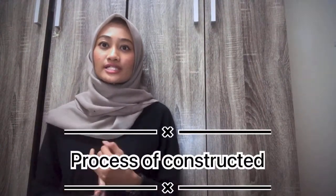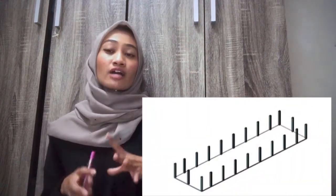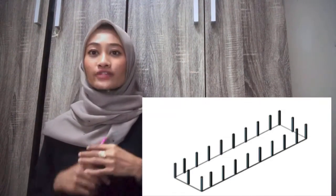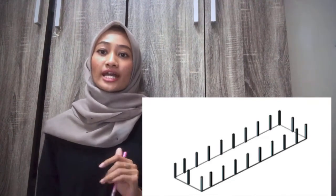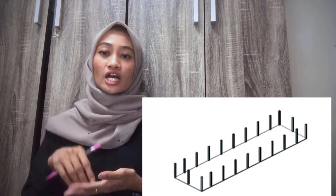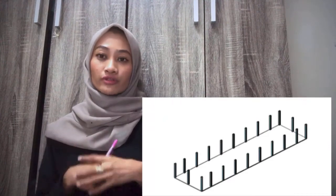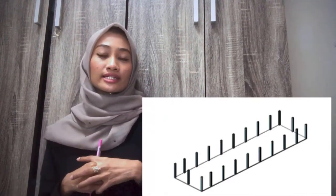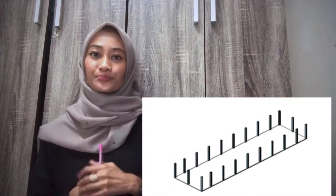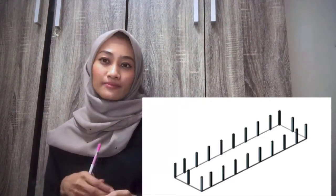First, after the completion of construction preparation, the layout of the structure is set. Second, the foundation of the columns is constructed. After the foundation is constructed, columns are placed using suitable machines and continuously checked by a supervisor for alignment. In the case of frame systems and slab column systems with shear walls, beams for the precast frame and column slab system are then placed.